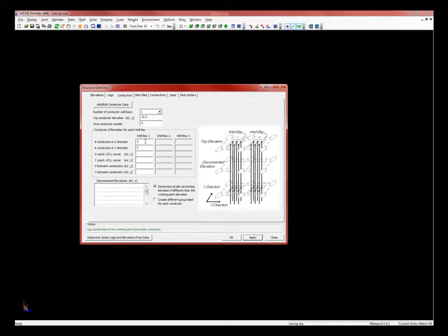Then we'll look at the drawings, and from the dimensions we had on the leg tab, we'll use that and come up with the coordinates for the lower left corner. So the X coordinate for the lower left corner is negative 4.5, and the Y coordinate of the same spot is negative 1.